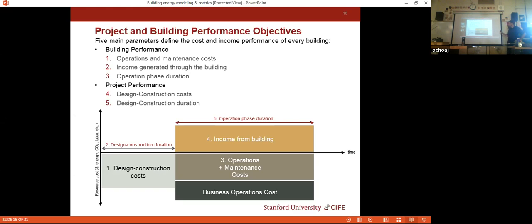If I gave another example here of a building where you say, hey, we don't want to be as efficient. One of the examples they used to give is that energy retrofits would go into a building, say like this building here, and they would seal the building. Let's say you blocked off the doors back here, and we sealed this building. And then we removed the fresh air going into the building and just put in a recirculator. We would create a building that would make everybody sick. But the energy cost would go way down. While we're making an energy efficient building, we're now increasing the cost of people's health.